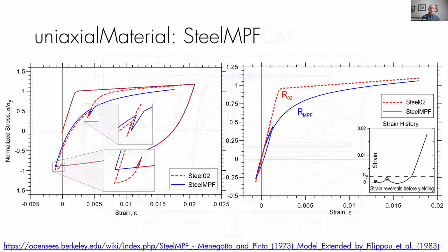And finally, part of this whole background implementation was Steel MPF, which is the Menegotto-Pinto-Filippou model. It's basically the same as Steel02 in a way, but improved.